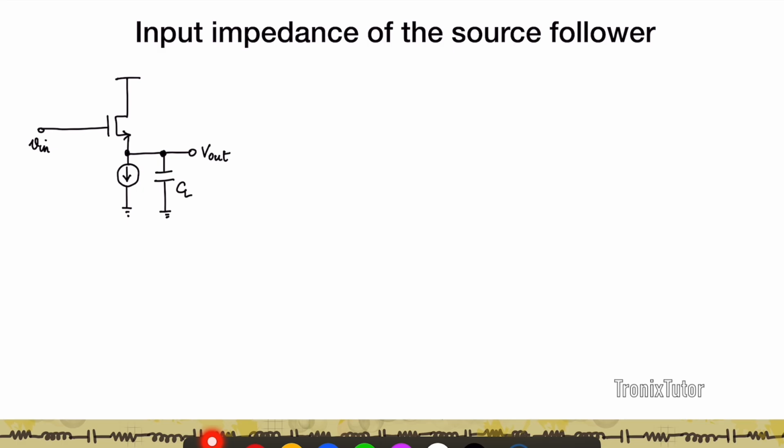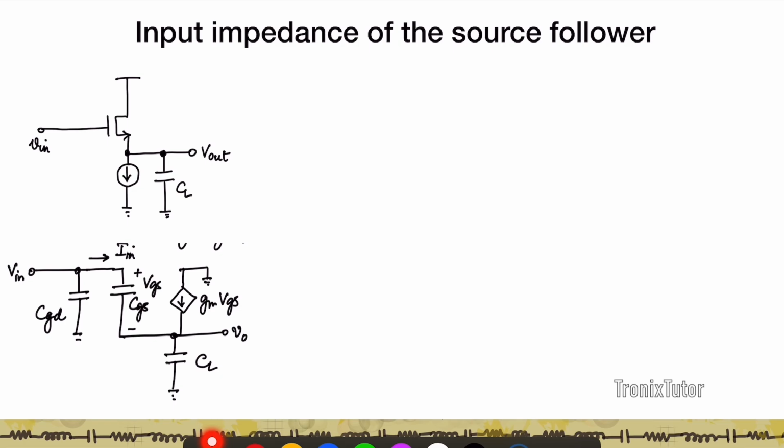Now let's look at the input impedance of the source follower, right? If you look at the input impedance of the source follower, again, we'll replace the transistor with a small signal circuit, assuming lambda is equal to 0 in this case. This is an ideal current source, so there's no load resistance. And if you neglect CGD for now, as I said, suppose CGD is small, what you see is Vin given by VGS plus In plus GMVGS into SCL, right? So this is going to be VGS plus whatever is the voltage drop across CL. This is essentially your I out or V out.